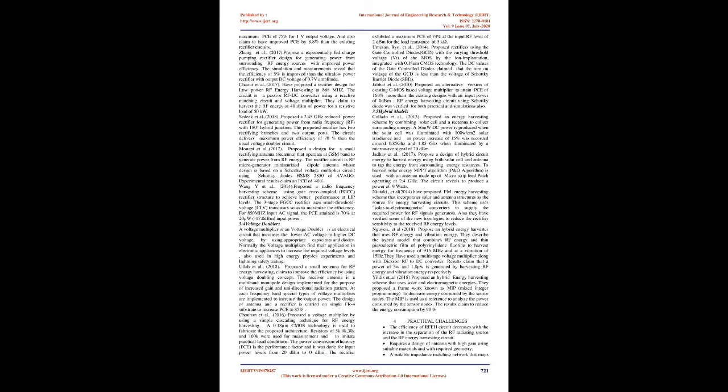The RF energy harvester circuit uses an impedance circuitry that is off-chip so as to increase the generated power within a specified frequency band of 902-928 MHz. The proposed RF energy harvester claims a PCE of 32% at -15 dBm, 32 µW, and produces 3.2 V of DC voltage to a load of 1 MΩ.